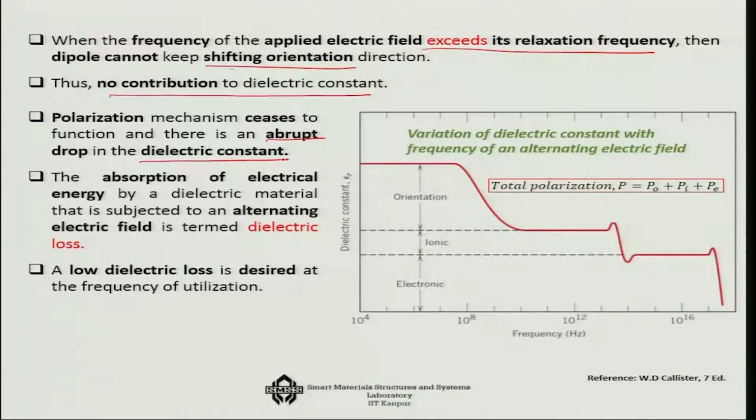So, you can see here the dielectric constant with respect to frequency. I am increasing the frequency gradually from kilohertz to megahertz, gigahertz level onwards, and the dielectric constant is initially stable, but then it actually fails. It comes down, then remains stable, and then further comes down finally.